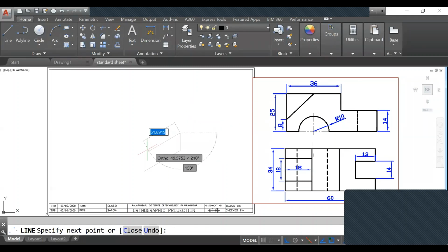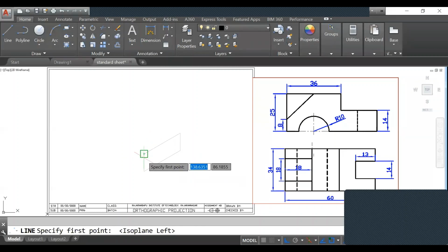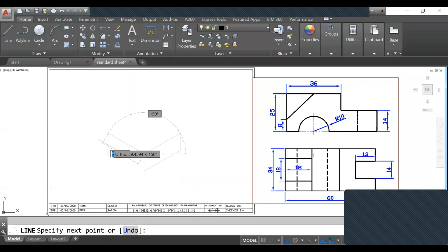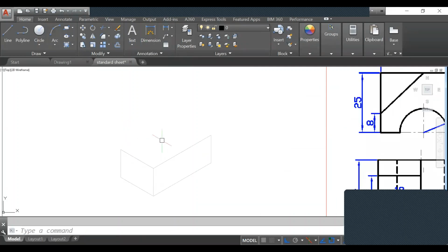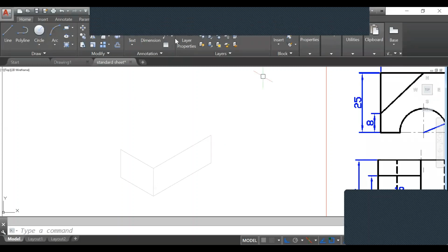From that each side you have to give the height. Getting? So Control E. This side width you have to give on this side. So width is 34. Then height I will consider here 25. Okay. Now this side 60 length, this side 34 width. Okay, parallel to each other.